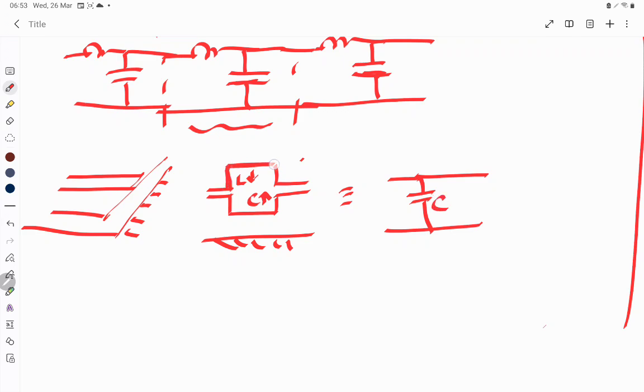So by making the top conductor width high, we can make it behave like a capacitor in shunt. Similarly, by making the top conductor width much smaller and running it for some length, we can model it as an inductor.